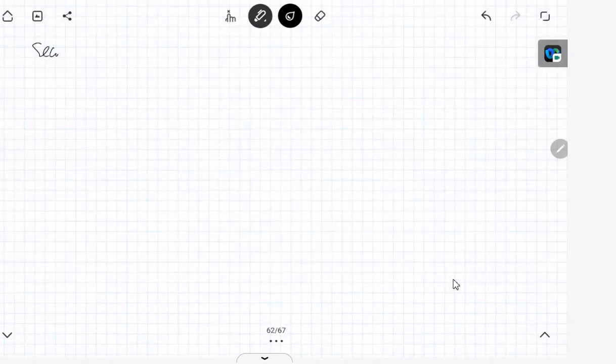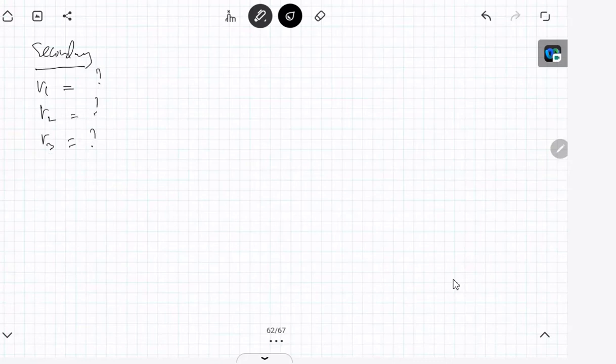Then secondary. So you will get the R value, R1. So you take the centroid, based on the centroid you get R1, R2 and R3. After you get that, you will calculate the polar moment. Use the formula given, so you will get it. Then for welding, you have to multiply by T. So, also T. Okay.